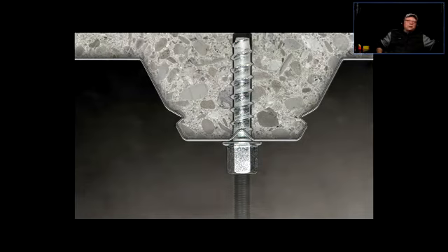So first you're going to have to use a regular steel bit and not a hammer drill, because if you use that, you're just going to dull the drill bit in 3 seconds, and you're not going to have much effect from your work. First you're going to drill through that, and then you're going to change the bits and use a concrete bit with the hammer drill to drill a hole, and then you're going to drive this thing into it. Here's the anchor, or whatever the spec sheets call for and the procedures according to whatever anchoring system you're going to use.